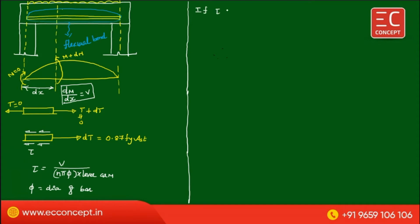If tau is less than tau bd, then there is no bond failure. If the developed tau is greater than tau bd, which is the limit, then there is a bond failure. If this condition is satisfied, then there is no bond failure.